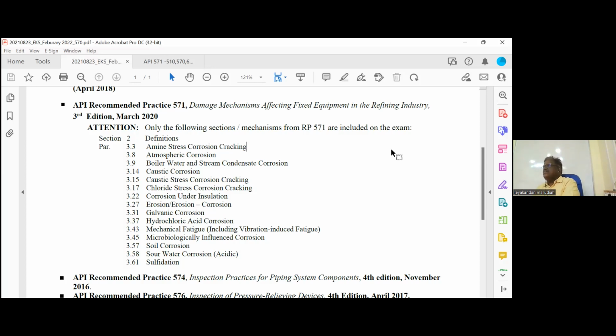Now, next one is eddy current. Again, similar to this, all are called electromagnetic NDT methods. What is the advantage of eddy current? What is the penetration of MPI? We say surface and subsurface. Subsurface up to what depth can we detect? 6 mm, theoretically, though practically it will be a little less than 6 mm. If you are using DC current, it can go up to 6 mm, whereas eddy current can go up to 13 mm, half an inch. Eddy current, again, we are using current disturbance only. We are using AC only.